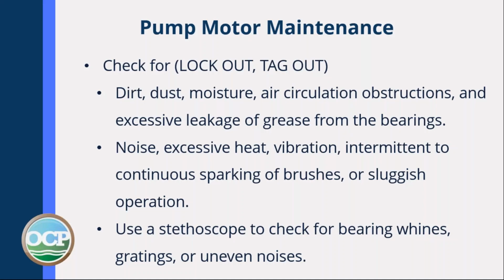When you're checking the motor, look for dust, dirt, moisture, obstructions in the air circulation vents, and excessive leakage of grease from the bearings. When the pump is running, check for noise, excessive heat, vibration, intermittent to continuous sparking of brushes, or sluggish operation. You check for bearing whines, gratings, and uneven noises. You can use a stethoscope for this or a screwdriver.